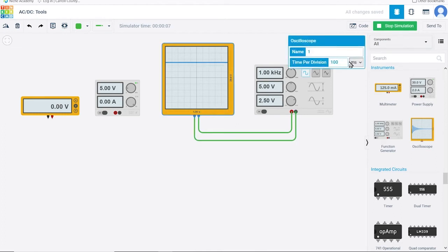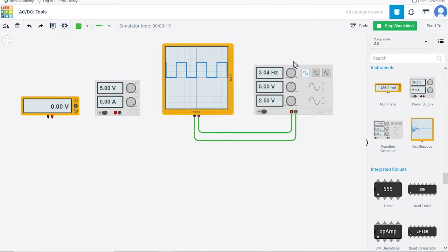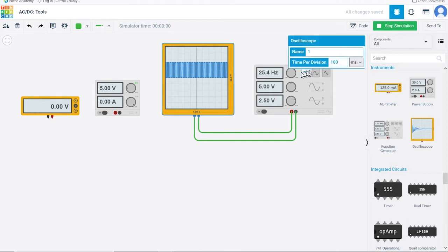Voltage and resistance are the easiest quantities to measure directly and work with. If the function generator is configured to output a DC square wave, that is, a signal that varies from 0 volts to 5 volts over each cycle, we can measure that voltage with the oscilloscope. A direct current is said to flow from positive potential to negative potential, or ground. Current only flows in one direction. An alternating current is one that is said to change directions once per cycle.